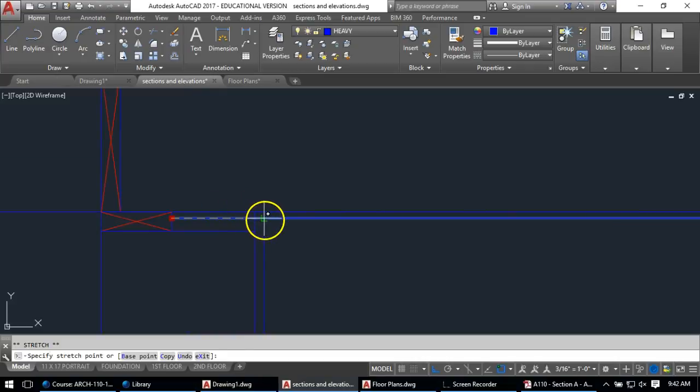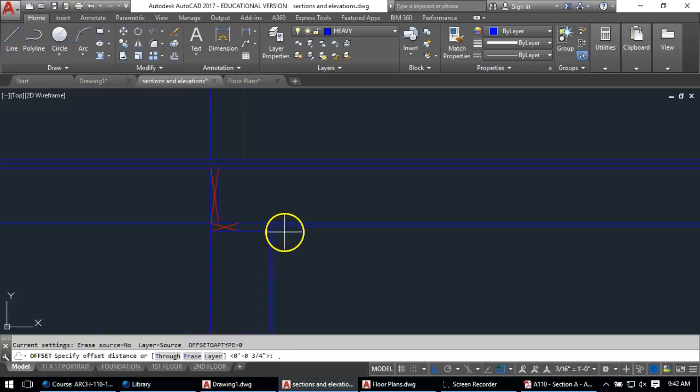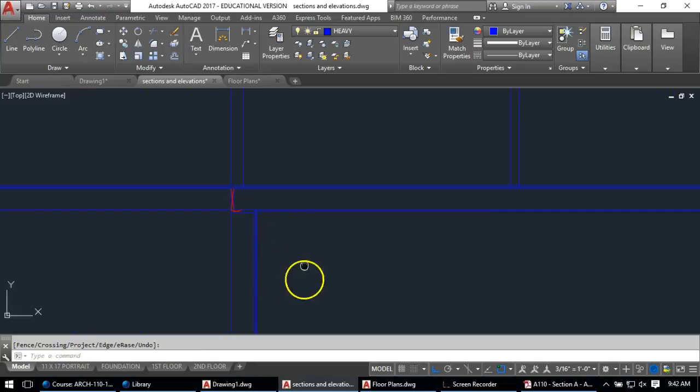And I can pull this back. And then there is the 1/2 inch drywall on the wall. So I'll offset it another 1/2 inch that way. And I'll let the ceiling gypsum come through on that way. And I'll check the bottom of it. So there we go. So here's where I want to talk about layers for a little bit.